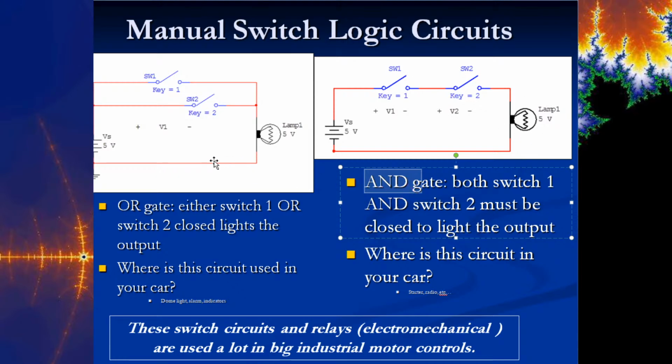The other operation is what you see up here, where you have the switches wired in what's called parallel. These are wired in series. These are wired in parallel. So when the current comes up to this node, it's got a choice. It can go through this branch, or, key word there, or it can go through this branch to illuminate the lamp.